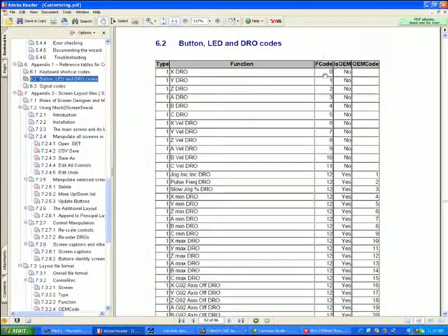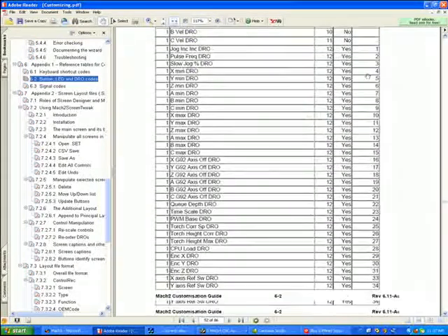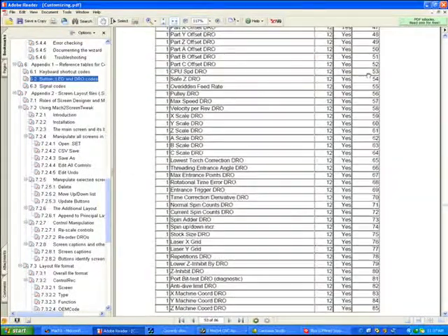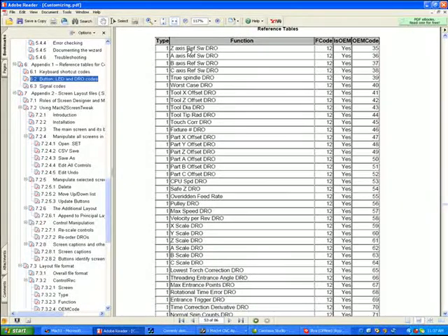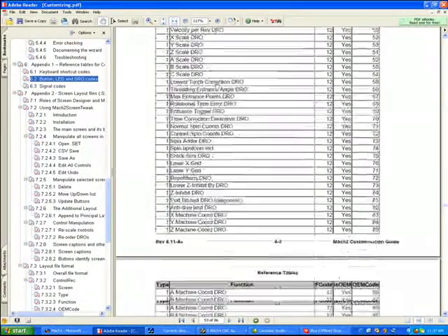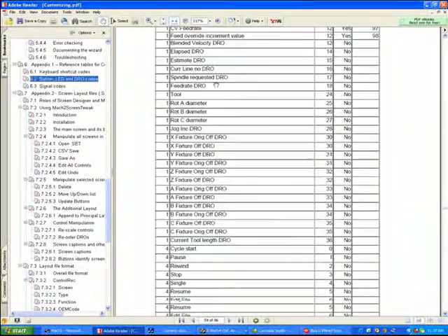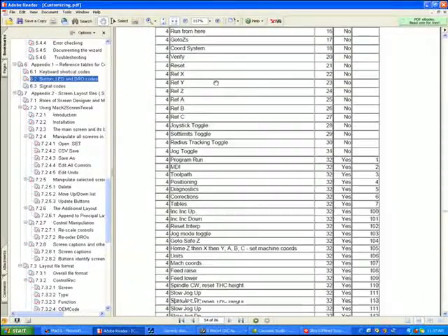If it's a function code you're calling, the command is usually GetDRO, whereas if it's an OEM code, it's GetOEMDRO. So if we look down the list, for example, we can see that the Z axis reference switch DRO, this is the position that you're going to tell a Z axis to zero to, the homing, is OEM code 35. So you can find out what value a user has set for this particular variable by saying GetUserDRO(35). There's a large list of DROs that you can get or set within the program.